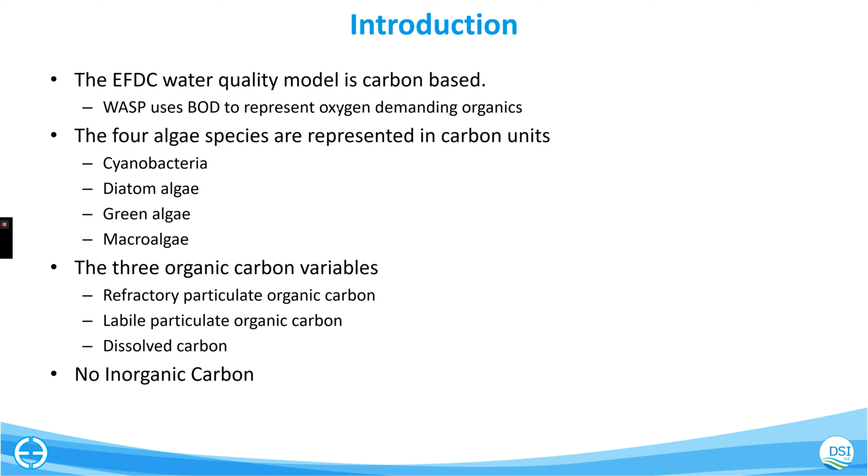Then within the refractory particulate and labile particulate, both of these classes settle, and of course the dissolved does not. That one just moves in the water column. And then right now, there's no inorganic carbon, and eventually we hope to get to next year having CO2 in the model along with alkalinity, and then we're going to be able to simulate pH. So that's actually in our development plan for EFDC Plus.